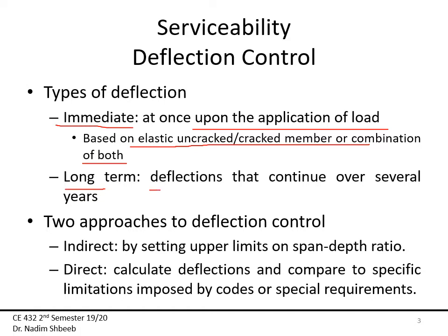Long-term deflection is a deflection that continues over several years, and that is usually due to creep of concrete that settles in after a while. We will be showing you how to calculate that.